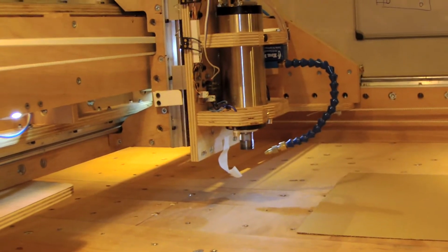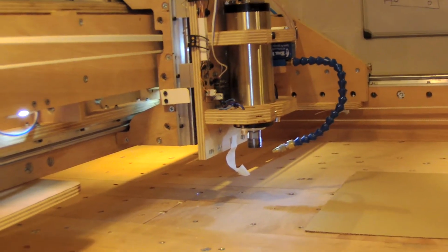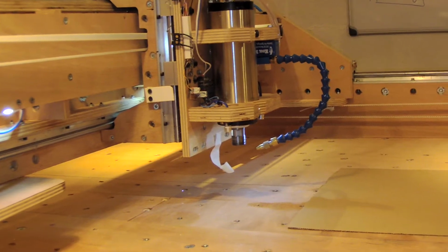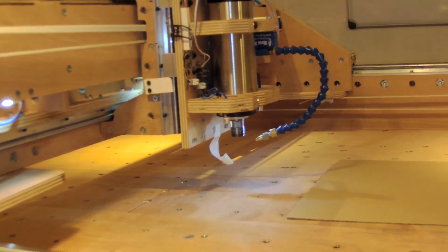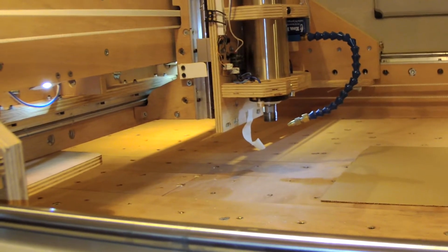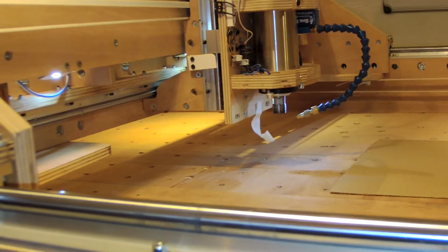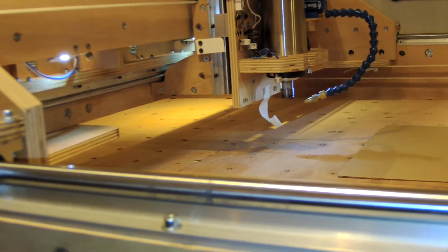There are some different techniques depending on the trade, the manufacturing, and the machine. But basically, it's often the same thing to define a point, either on a stock or somewhere on the machine, to define the 0 position. So now the machine knows exactly where the head and the cutting tool are in space.